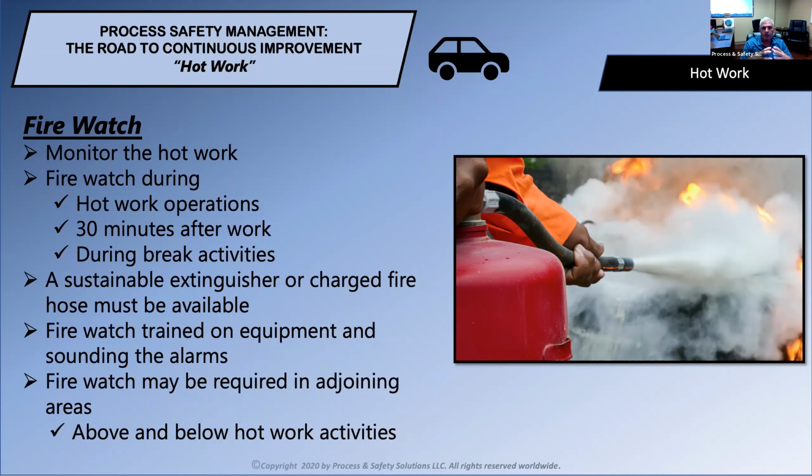This is one thing we see quite often. The hot work is going on, the people doing the hot work decide, well, we're going to take a 15-minute break, and all of them leave, including the Firewatch. And the Firewatch must remain there during that break and 30 minutes thereafter.